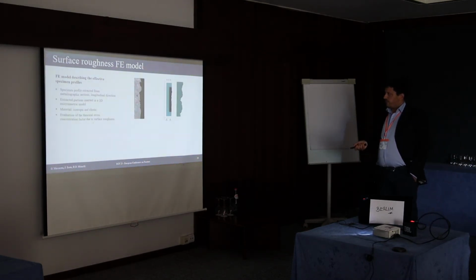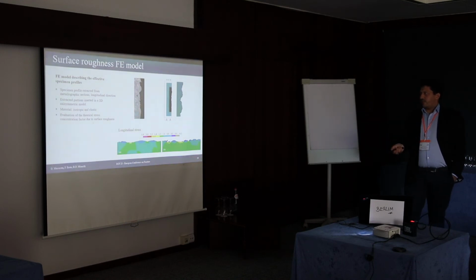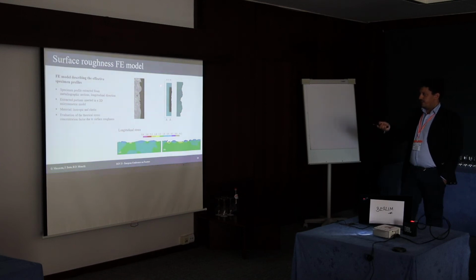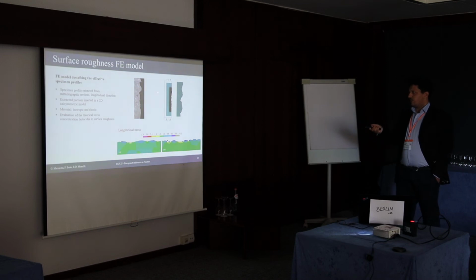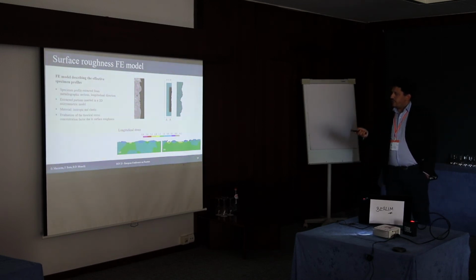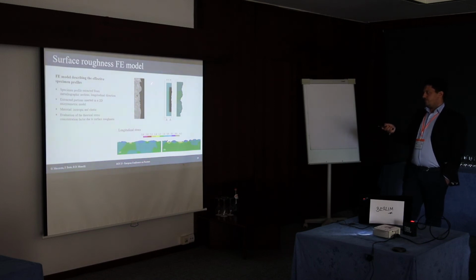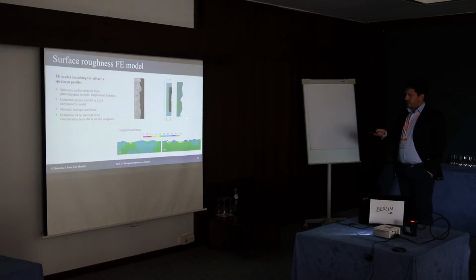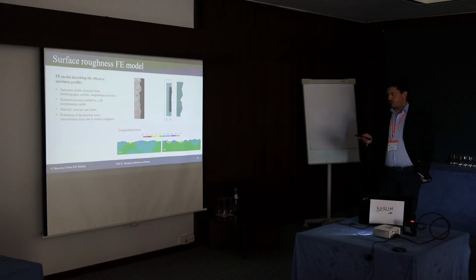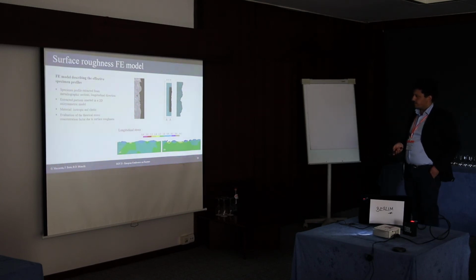First of all, we produced a finite element model simulation that takes into account the profile of the specimen. From the metallographic investigation, the profile of the specimen was extracted, with some smoothing, obviously, to avoid the powder that is on the surface, and a dedicated CAD model was created for each portion of the specimen. Then we ran the finite element simulation of the specimen with an axisymmetric model, with the material considered only isotropic and elastic in this first approximation.